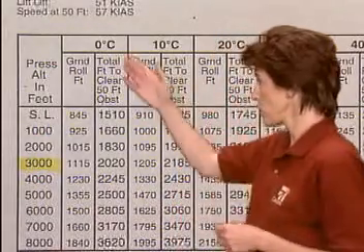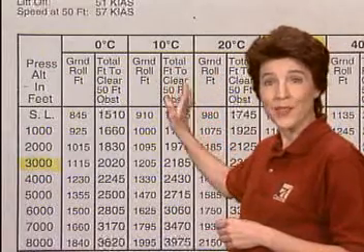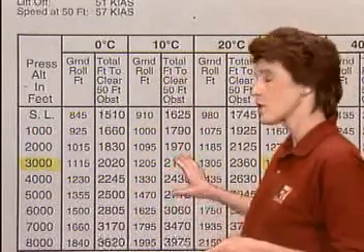Now, as you look at the takeoff chart, you'll see pressure altitude here, and across the top, temperature. That's right, it's another density or performance altitude chart in disguise. Once again, instead of printing the value of the density altitude, the engineers plugged in the performance you can expect at that density altitude. Remember to keep your results conservative by applying the next higher temperature and altitude values, rather than interpolating. It also keeps the arithmetic simple, and if we pilots need anything, it's simple arithmetic.